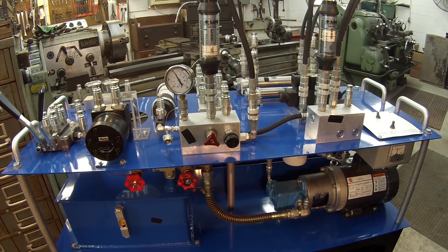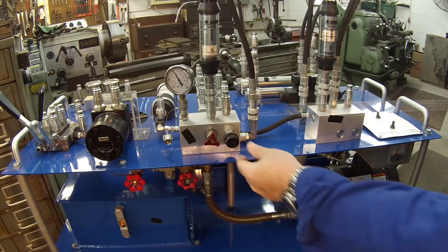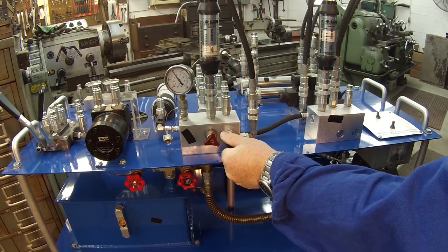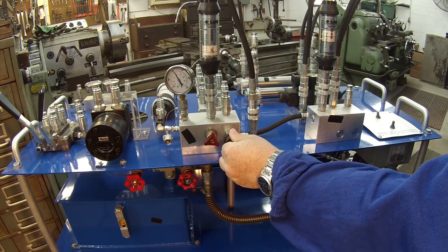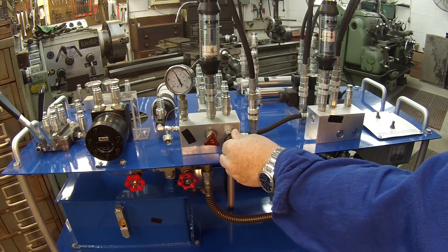Alright, you see on this gauge right here, I'm showing 400 psi. The only reason I'm showing that 400 psi is because I have my bypass valve closed and I'm forcing that oil across this spring inside this relief valve. Okay? So you'll see if I move this relief valve in and out, the pressure goes up or down based on the resistance to that oil that I'm pushing across that orifice right there.